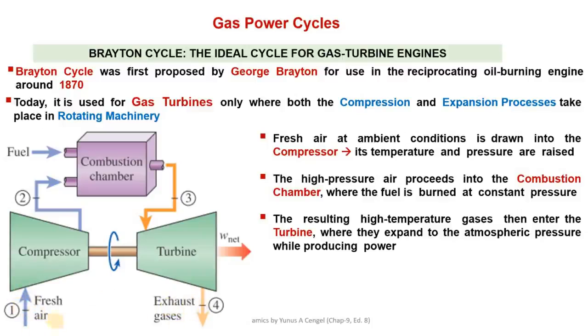And so this is not actually a closed cycle, it is an open cycle because we are not using this working fluid again to complete a cycle, as it was in the steam power cycle. In case of steam power cycle, the same steam was reused, right, in the whole cycle. So that was definitely a closed cycle, but this gas power cycle is an open cycle. Mass is entering and then mass is leaving, right?